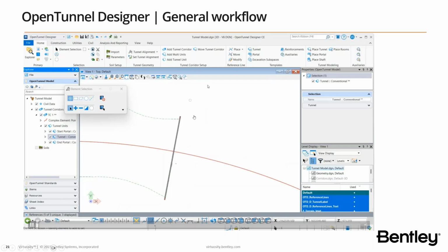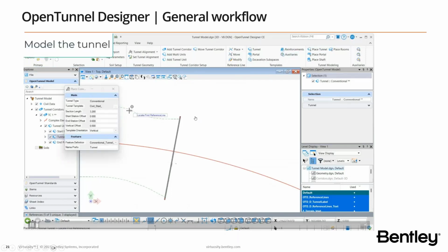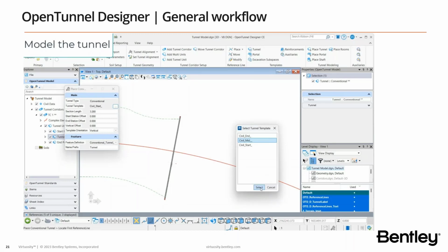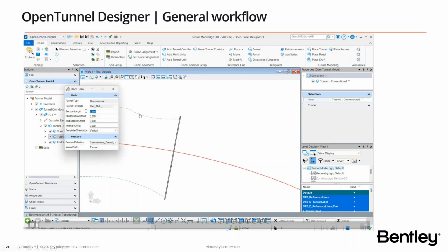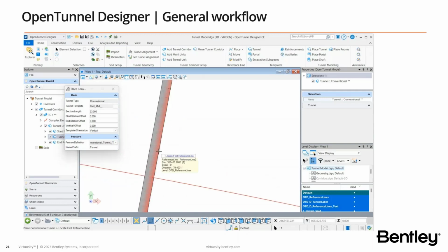We are switching now to the second unit. In here we have the actual tunnel. We are dividing the tunnel in section lengths. Basically, these section lengths can be interpreted as an excavation advancement length. I am excavating on 32 feet, and I am creating the lining, and then I'm going again on the next step of excavation. And this is of importance also for the transfer to Plaxis.